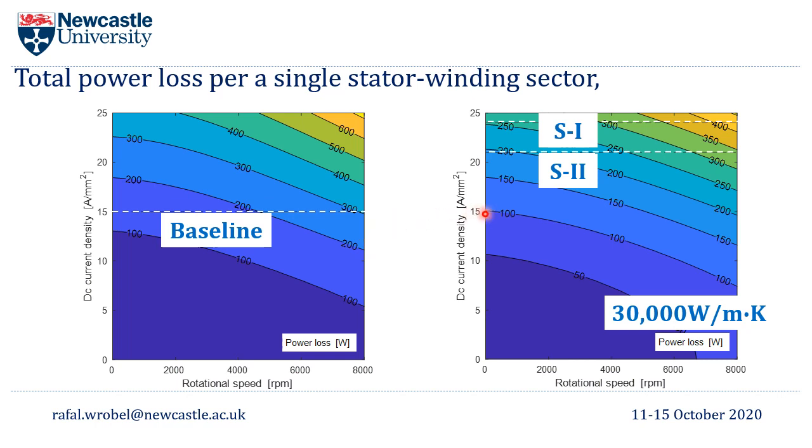For the same current density, the alternative winding generates less loss, and this is associated with the lower volume of conductors. The alternative heat pipe based systems, so S1, supplementary, and S2, primary, allow in general for higher loss to be removed from that stator winding assembly, but in both cases, as we increase the operating speed, that initial current density is being reduced significantly.